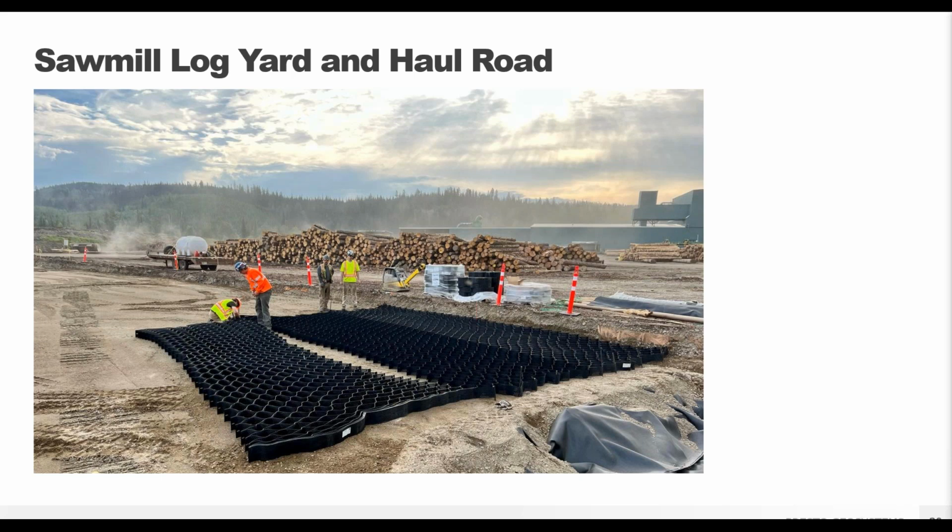This is a good place to mention why you might use a geotextile. And really, you're going to include one when you have these really soft soils, because including the geotextile helps prevent over compaction and punching into your soft soil environments. It helps spread the load, helps create that mattress effect. So it kind of acts like a snowshoe.